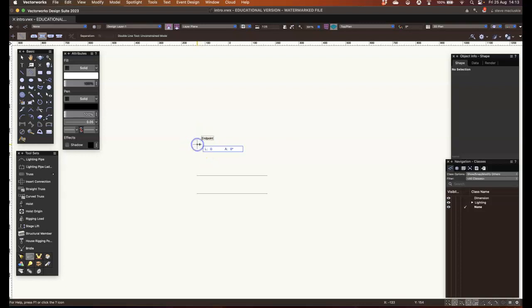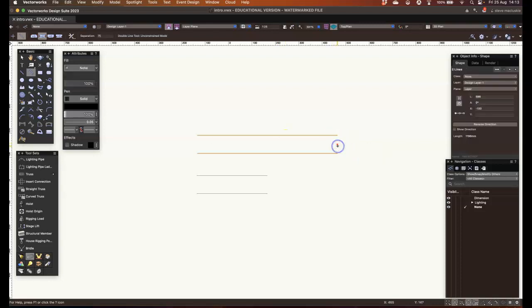Center control line, I'll just zoom out a little bit. Hopefully, unsurprisingly, if I draw, it'll be the center of the double line that's drawn, with the lines evenly spaced out from the center to make the 75 mil. The bottom control line, which will be the exact opposite of the one that I did here, will be as I draw that, the control line at the bottom and the separation to the top.